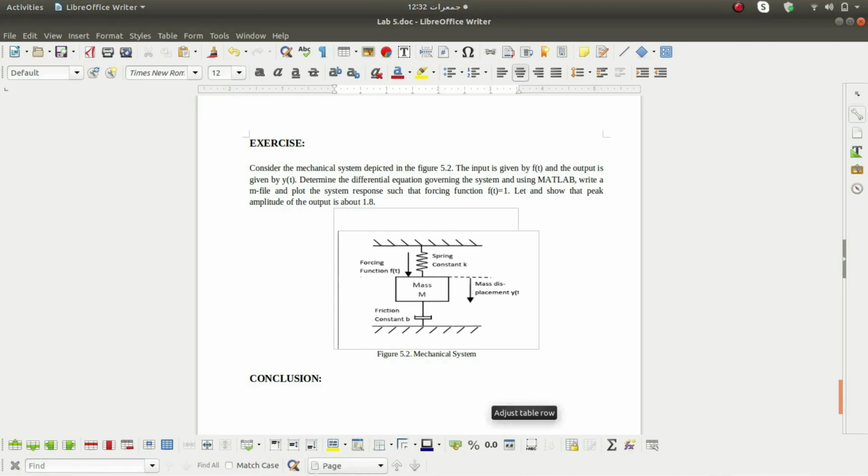You have to derive its mathematical equation using the same method we have discussed and solve it in MATLAB. The pattern will be the same. Just keep in mind what we are doing in the examples: first implement the examples and then implement the exercise in the same way. You have to use the ODE function or dsolve to solve this problem.